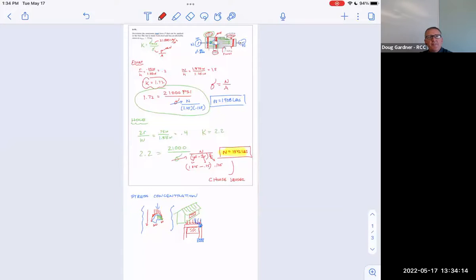I mean, people have thought about this stuff for 100 years. And so you'll be working on something and somebody has the great idea to design a weakness into it. And it'll be up to you to decide what kind of material that little bolt is going to be and what diameter do I pick? Because practically speaking, if it breaks because you got into some tall grass, that might get a little old, right? Like it broke too easy. But if it didn't break when you hit a rock or something, that's not so good.